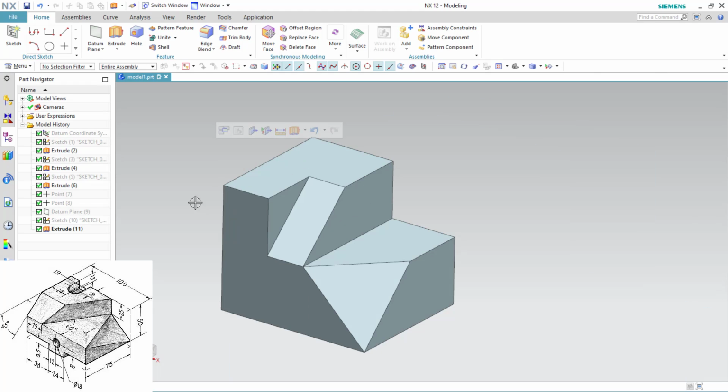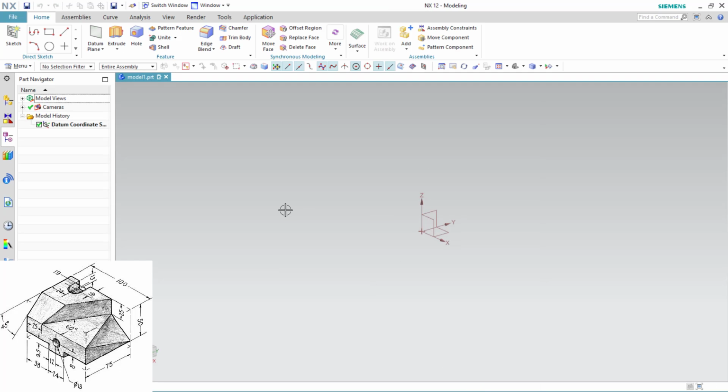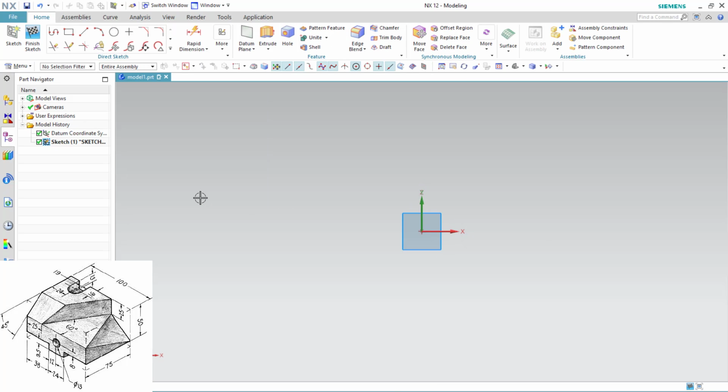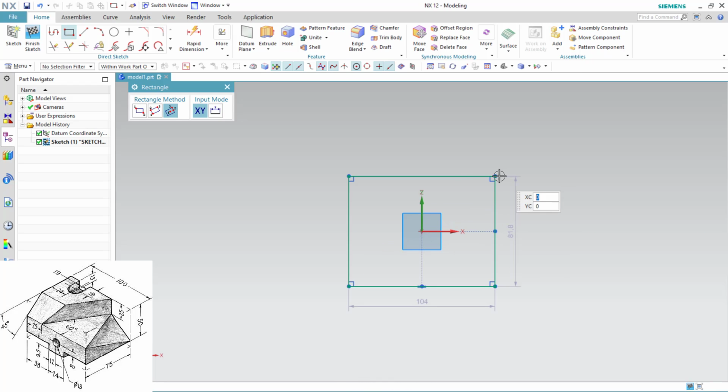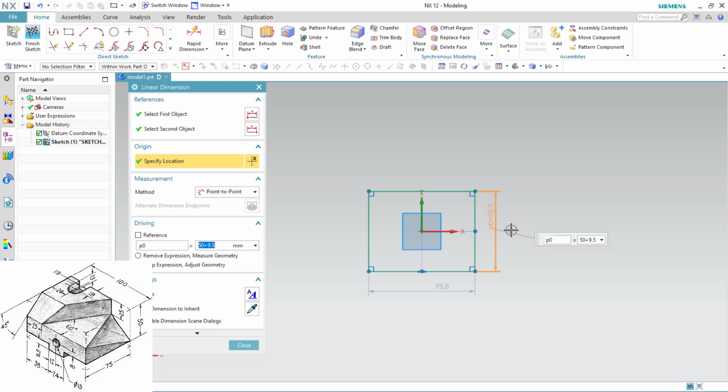Yeah, so let me just deal with this model. You can analyze now how exactly it is. So best way to start with this is to create any of the front plane or right plane is fine. So right side view or front plane, like the front view is also fine. So I'll deal with the center rectangle this time. So dimensions, can assign it. It is 50 plus 9.5 because extended extra portion is there. The total distance, the bottom one is 100, I believe. Yeah.